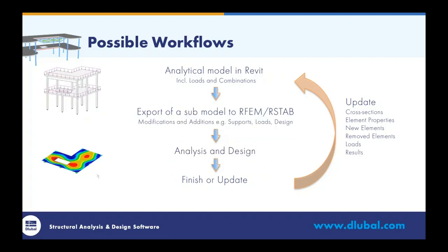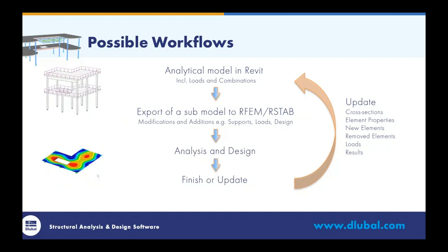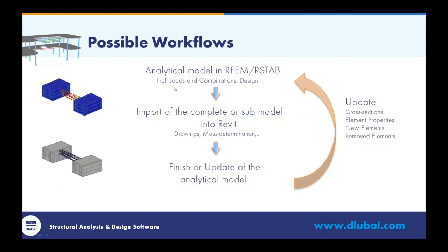These workflows, I mention usually Revit in this document, in the PowerPoint. They are, however, applicable to Tekla as well. So the first and the second workflow are more or less identical with Tekla. Only the third workflow, where we start in RFEM and export to Revit, we do not have that option to update the RFEM model in Tekla. So whenever I export from Tekla to RFEM, I will create a new file. Only Revit offers me the option to update my RFEM file.